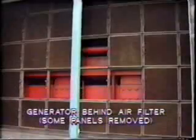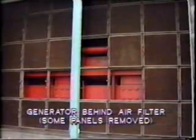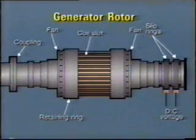The cooling system is a vital component of generator operation. As we mentioned in the last segment, the amount of power which a generator can supply is limited by the temperature rise of the windings. And therefore, the more efficient the cooling system, the more load can be placed on the generator. For most gas turbine installations, air cooling is employed, usually open cycle. The air is actually circulated through the generator by fans, which are fitted at each end of the rotor.